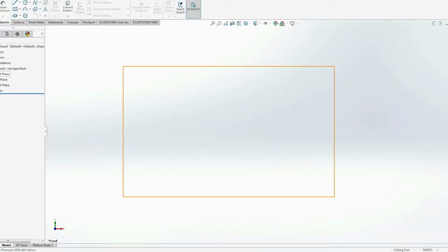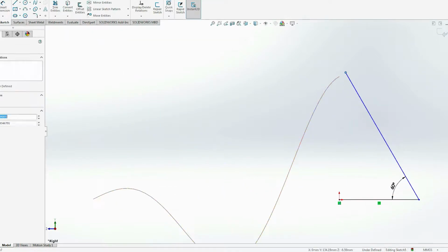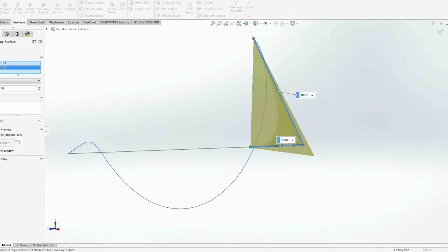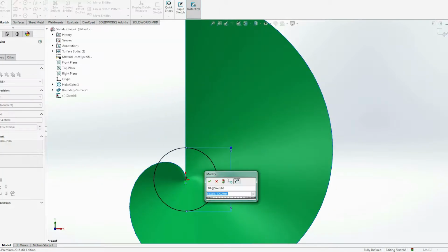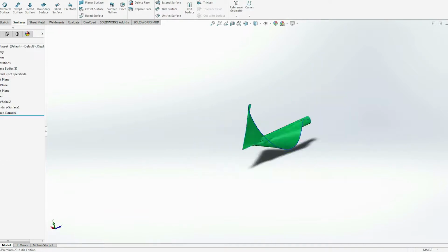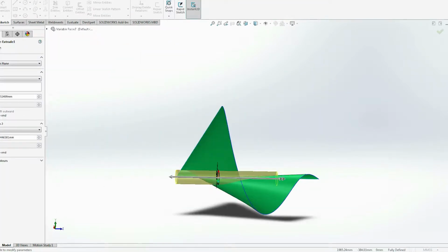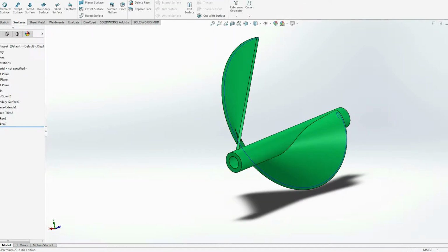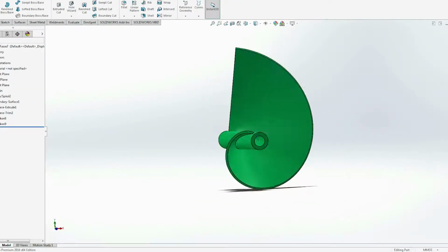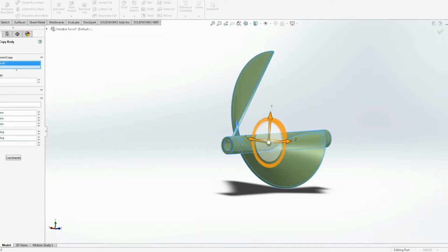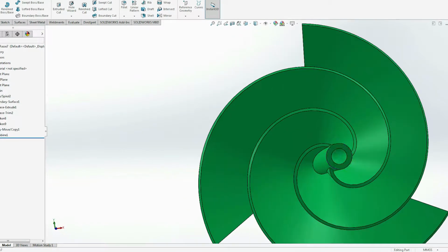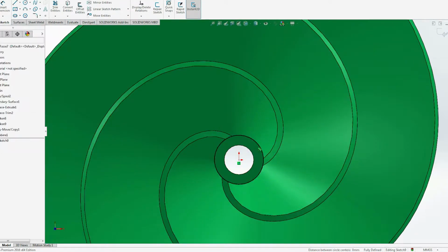The design was made possible in a CAD software called SolidWorks by simply sweeping the blade profile along the fixed diameter helix and removing any extras of the blade by revolve cutting. 2 Archimedes turbines were constructed. The first one is a constant angle design, where the blade angle does not change along the axis of the turbine, while the other one is a variable angle design, where the blade angle changes along the axis of the turbine.